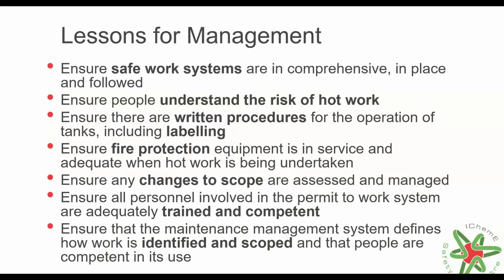Let's look at the lessons for management out of the safety law. So here it's really important for managers to ensure that their safe systems of work are comprehensive, in place and followed. They need to ensure that people understand the risk of hot work when it's being undertaken. Ensure there are written procedures for the operation of tanks, including adequate labelling. Ensure fire protection equipment is in service and adequate when any hot work is being undertaken. Ensure any changes to scope are assessed and managed. Ensure all personnel involved in the permit to work system are adequately trained and competent.